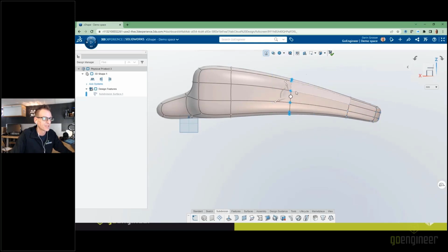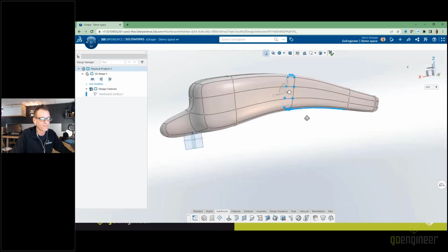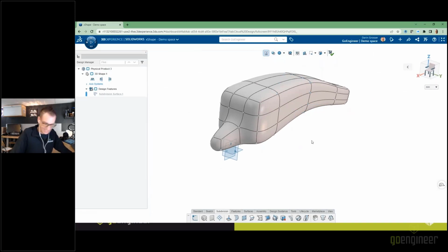And if I grab just this loop in the middle, that's going to enable me again to grab those edges and twist them and really deal with a little bit more of the shape that I want to add to these. Okay, this part is most definitely symmetric, and that happens a lot with organic geometry like this.